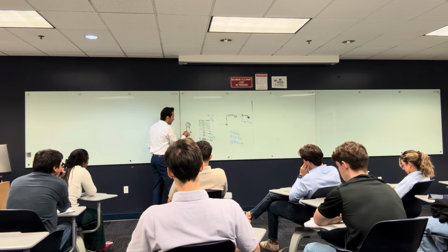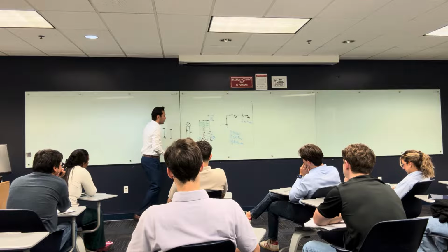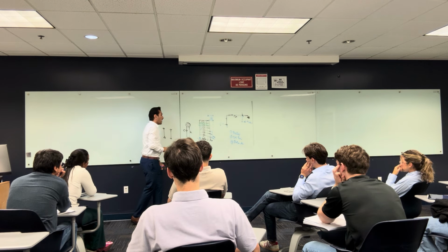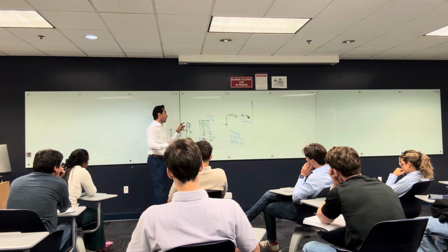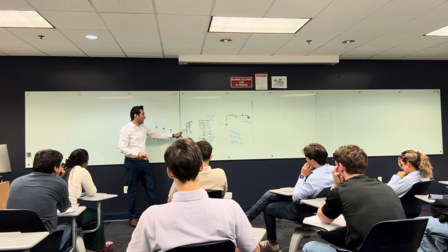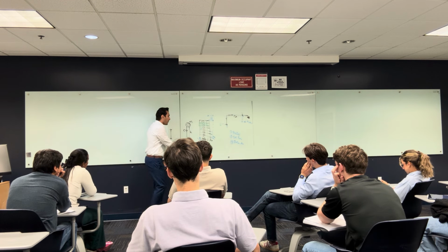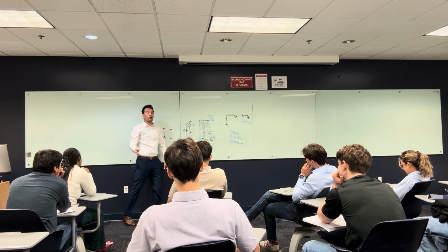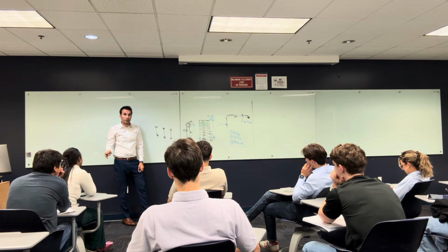we usually put the damping like this, like the piston logo, like something like this. And we call it C. If I was able to find the equivalent mass of the structure, and the equivalent stiffness of the structure, and the equivalent damping of the structure, and find this system that is going to generate the same delta that you have here, that is called the equivalent system of the structure.